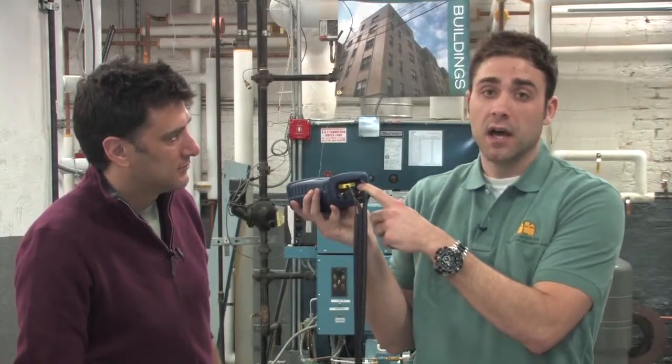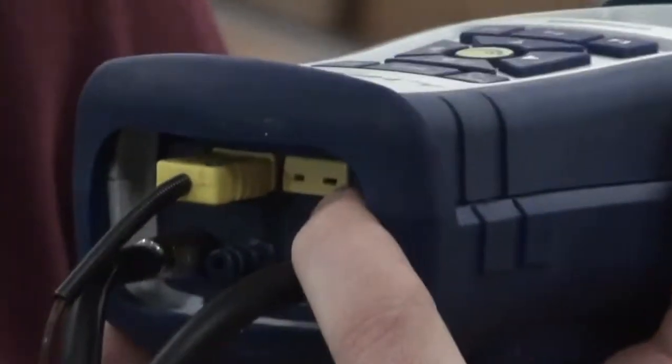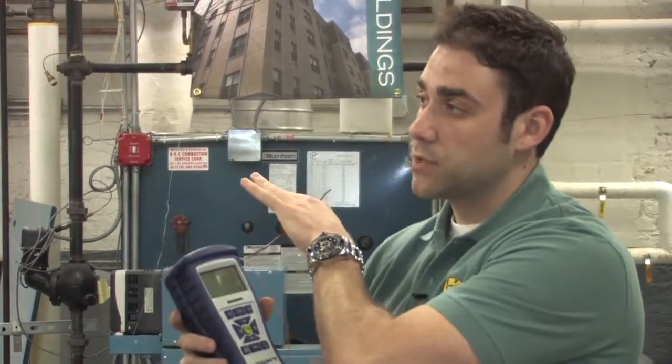The air setting, this one is going to be used when we have sealed combustion units, when we have a unit that's actually pulling its combustion air from the outside. So we want to measure whatever the combustion air is coming from, we want to make sure that we sample that temperature, because the analyzer, what it's doing to get stack temperature, it gets a net reading. So it's not the actual flue temperature inside the actual flue pipe, it's actually that minus the ambient room temperature.